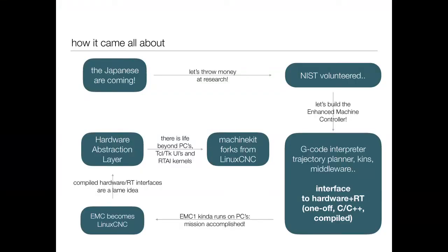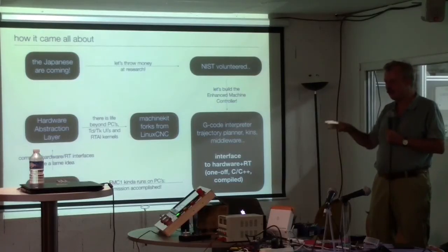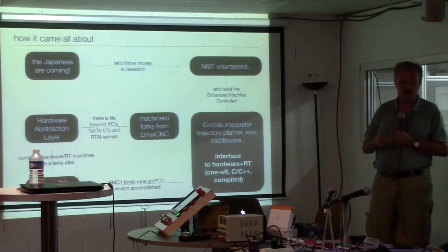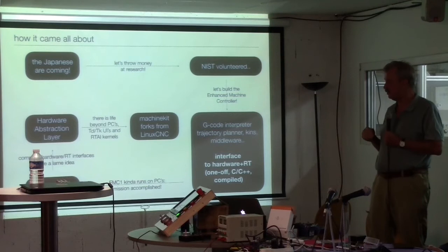We forked from Linux CNC with a particular emphasis on going multi-platform, supporting a wider range of embedded boards beyond the PC platform, focusing on the HAL layer, and bringing in newer software components. We had to dump TCL/TK. Nobody's using it anymore. All the programmers are retired, which I understand. It had to happen. So Alex did a lot of work of bringing Qt-based user interfaces into this space.